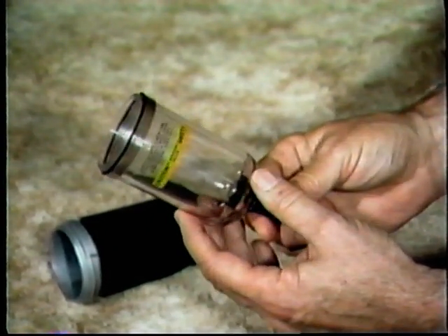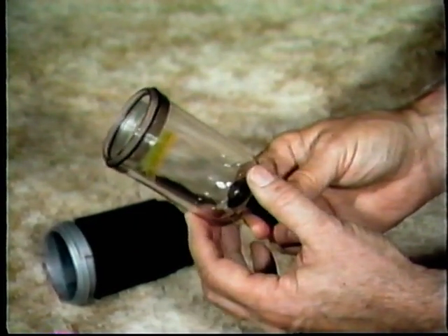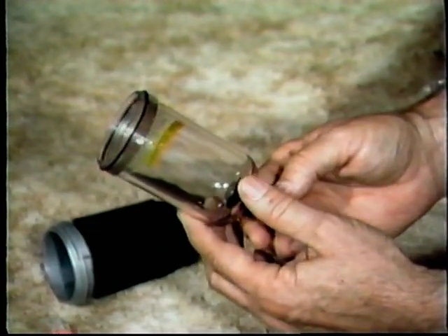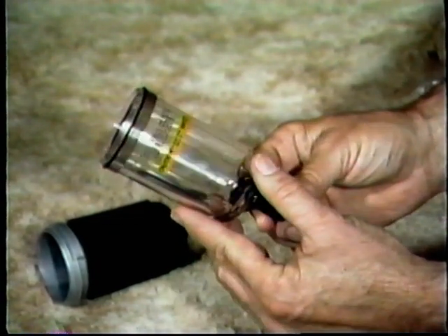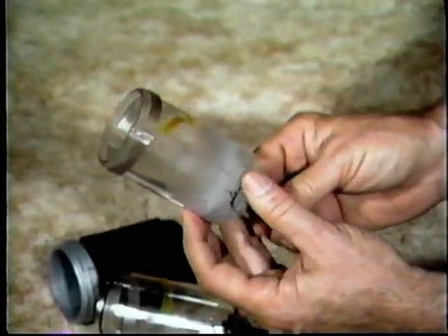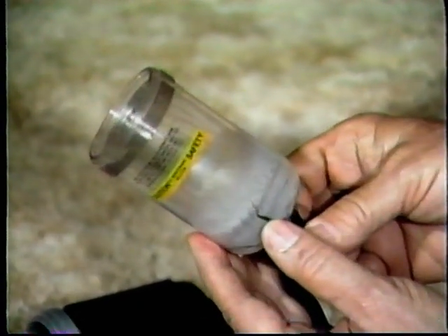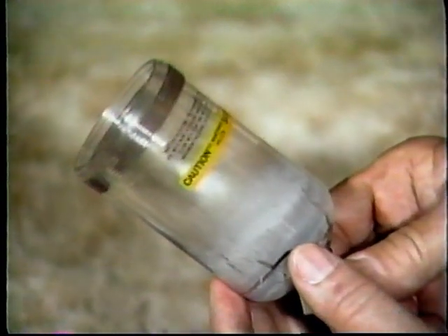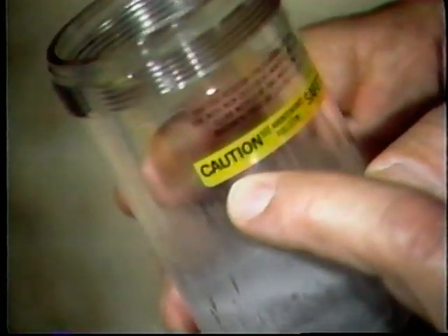Polycarbonate is a good material for bowls because it is transparent and tough. It is suitable for use in most industrial environments, but it shouldn't be used where it can be subject to high impact blows or to temperatures outside of the rated range. This bowl illustrates another point. As with most plastics, exposure to certain chemicals, generally any type of solvent, can cause damage. So before you install a polycarbonate bowl and place it in operation, check to see what cautions or special directions are provided by the manufacturer.